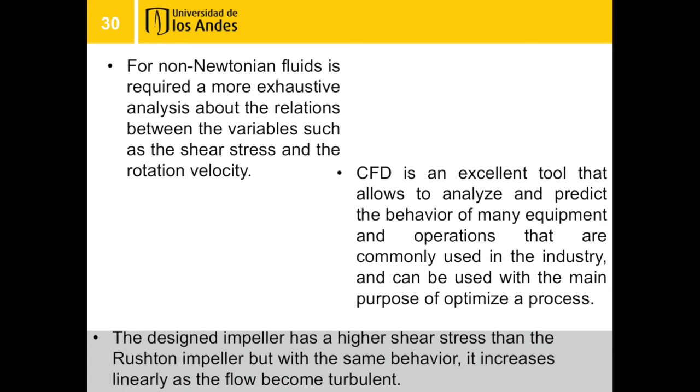The design impeller has a higher shear stress than the Rushton impeller but with the same behavior. It increases linearly as the flow becomes turbulent.